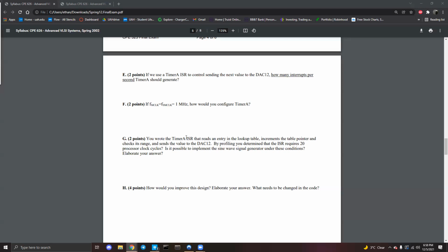So what is that going to produce? Basically, you could want to be reading in 1 microsecond values while you're calculating. It'd be 20 microseconds. In this case, I believe it's 50 clock cycles. So yeah, he says his answer is timer A generates an interrupt every 50 CPU clock cycles. The time required for the ISR is only 20, so yeah, you can speed it up, and that's true.